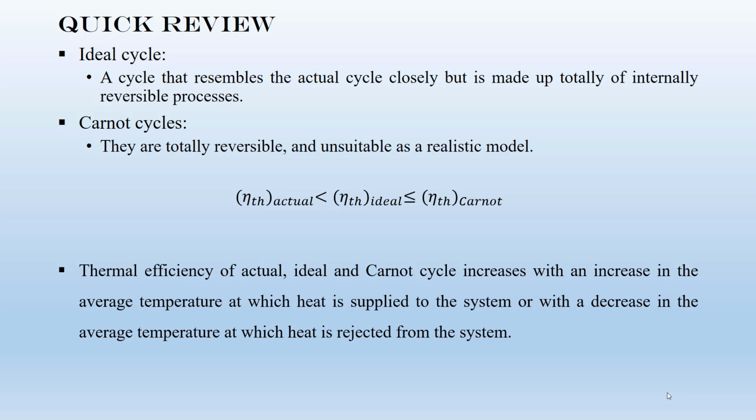If you want to increase the thermal efficiency of these cycles, I mean ideal, Carnot, or actual cycles, we need to increase the average temperature at which heat is supplied to the system, or we need to decrease the average temperature at which heat is rejected from the system.